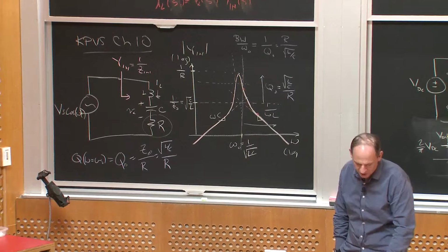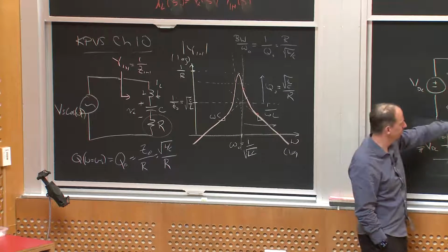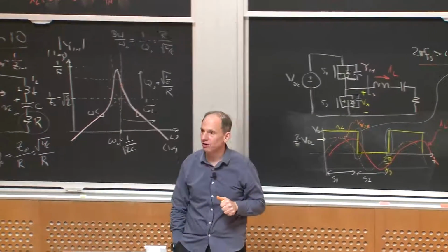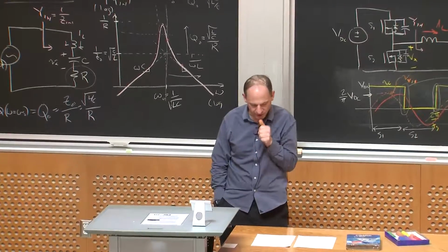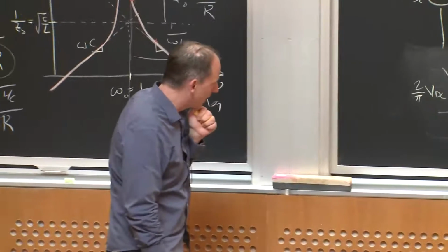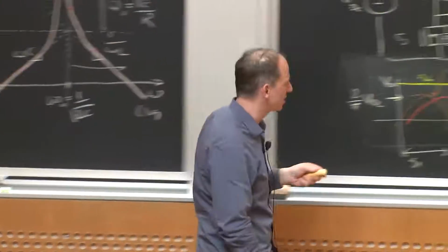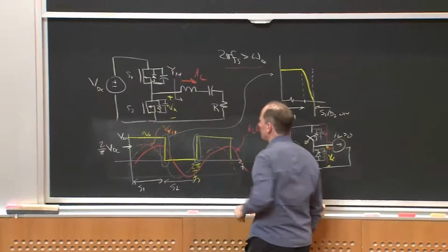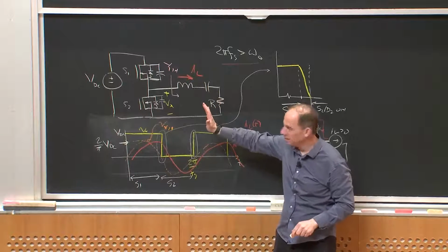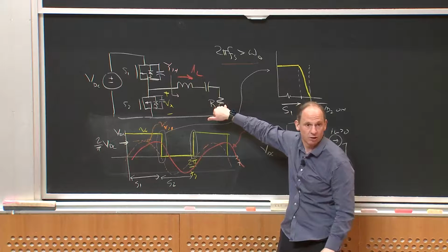Now, what's nice about this series resonant inverter circuit? Well, the first thing I said is we get 0 voltage switching for our devices, which is really helpful for efficiency. Notice also that if I modulate power, let's assume R is fixed, a fixed resistance, and I modulate the power by modulating the frequency, I get lower power by making this resistor current lower.